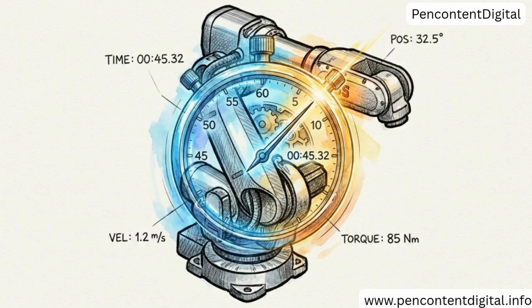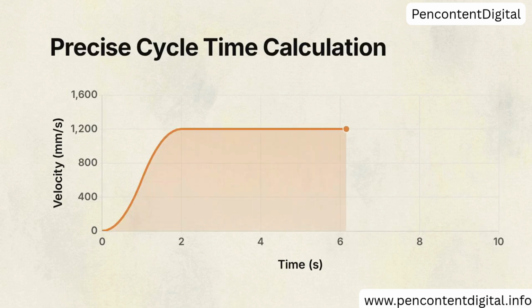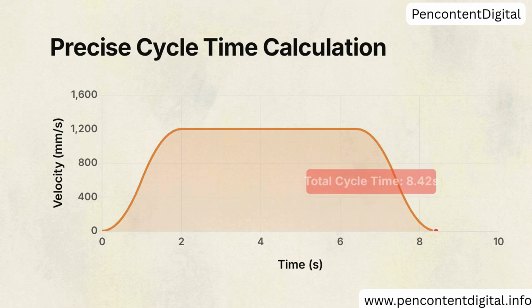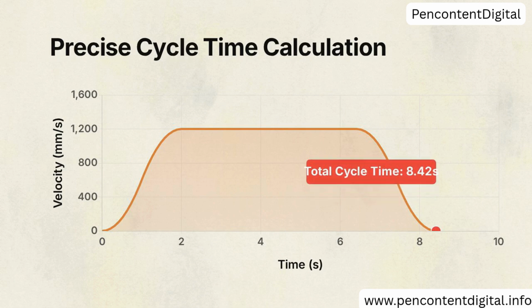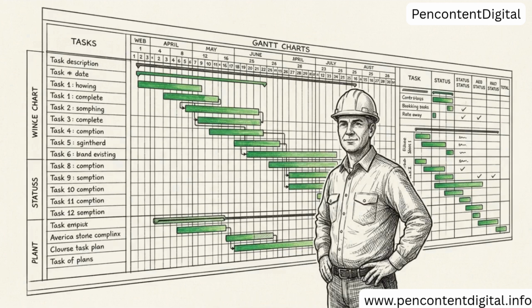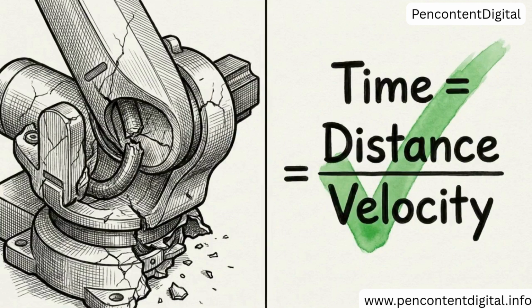Validating the physical space is only the first step. The system must also validate time. Because the software knows the precise kinematic profile and speed limits of the robot, it calculates exact operational cycle times based on the validated path. This cycle time estimation allows plant managers to integrate the robotic cell into factory production schedules and optimize resource allocation. Running these virtual trial and error cycles eliminates the risk of hardware damage while replacing scheduling guesswork with mathematical certainty.